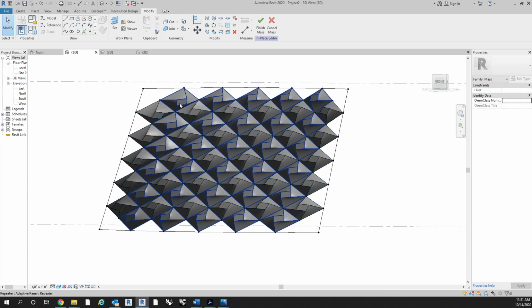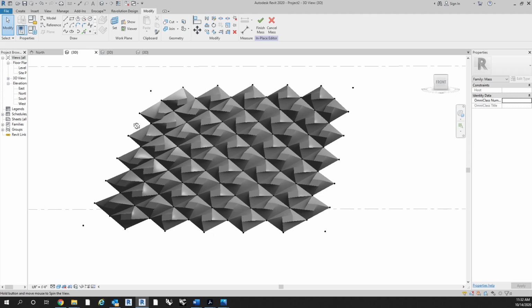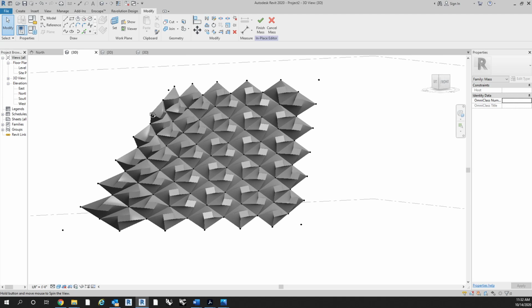Because I know a lot of you were having issues when you're creating the pattern-based families that sometimes if the geometry of the surface was too complex, or if certain things weren't working nicely within Revit, it was kind of just extending the panel out and not giving you that clean cut. So this way we can make sure we can build our own edge panels and be a little bit more prescriptive about it. So that, I believe, is everything.